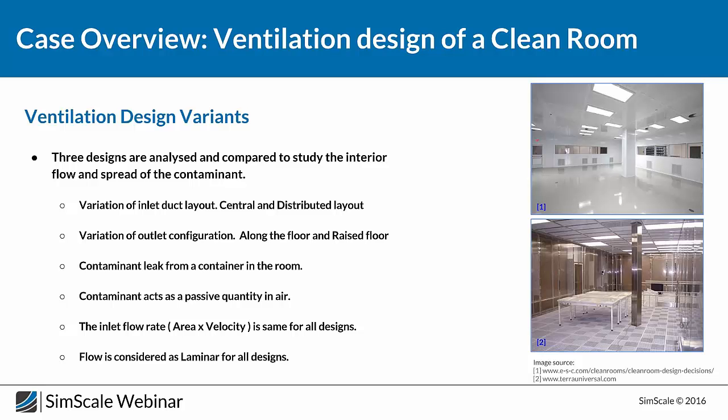The reason is that the size of the particles that normally are interesting in these applications are quite small. Considering that and the kind of velocity profiles that are typical of these applications, there's really very minimum, if any, effect of particles on the flow. And these particles are so small that they essentially follow the patterns of the flow. That's why we use passive scalars.